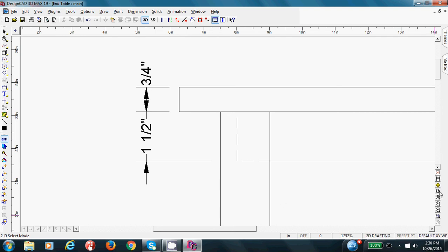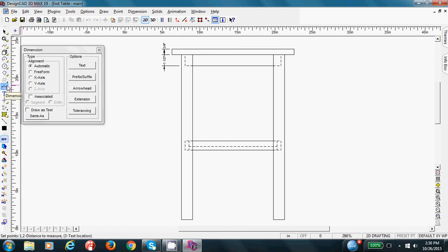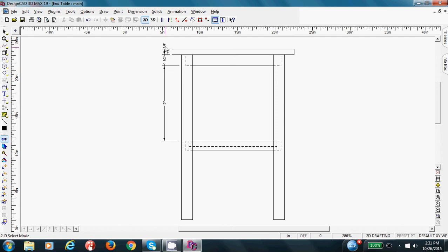Let's zoom back out. We've got two nice dimensions. Now we want to have a dimension from here all the way to here. Get that dimensioning tool. Everything is set up because I'm clicking from this point, so it'll maintain that 0.8 gap to this point. I don't have to do point relative, so I'm just going to right click to this and everything lines up nicely.